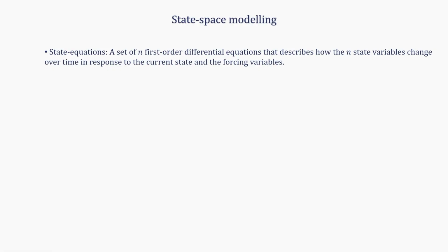Okay, now we know what are state vectors, what are state variables, what are state space, all these words we know. Okay. So, the first thing, like in case of modeling with external view or the transfer function modeling, what we did was, the first thing to identify was what was the output and the input, right? And then we found out the differential equation, or experimentally we came up with the transfer function of the system. In this setup, the first thing that you need to identify is what are the states of the system.